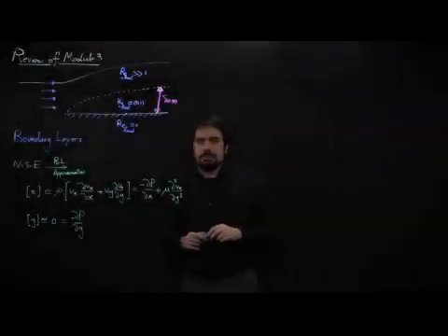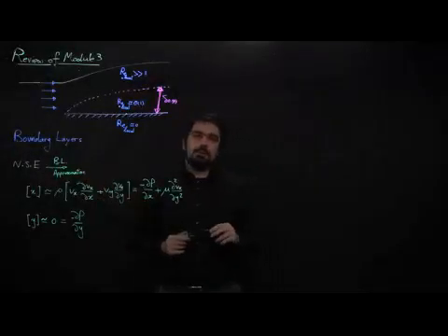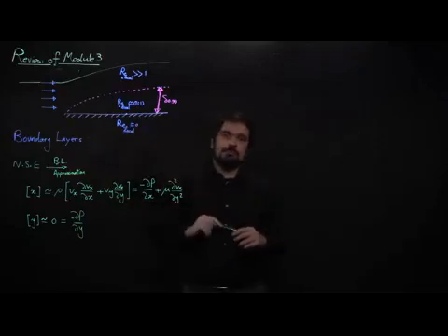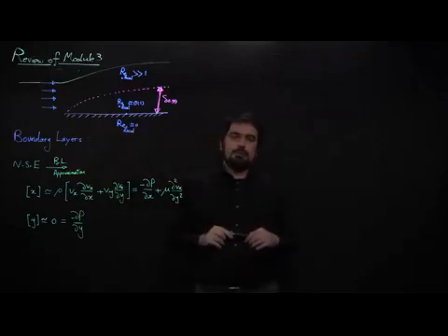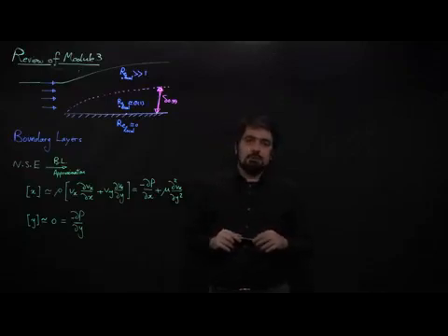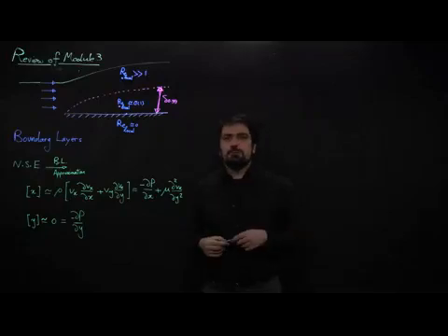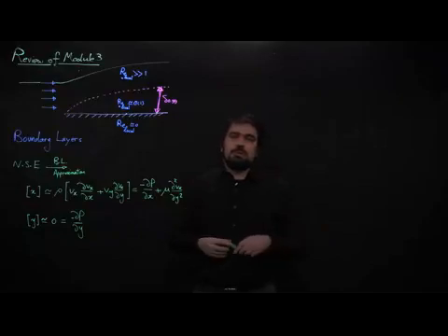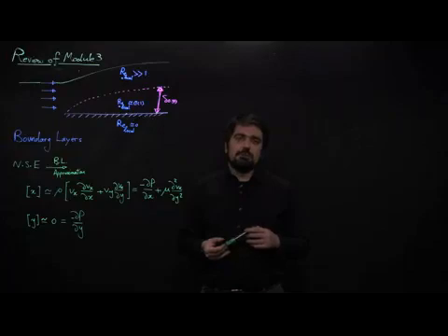Hi again. As we discussed in the last video, the idea of vorticity and the generation of vorticity at a rigid wall or boundary had to do with the no-slip condition in a real flow. When we discussed potential flows, the drawback was that we ignored the viscous terms, which are usually the second order derivatives. Because of that, our equation turned into a first order equation, and then we couldn't have all the boundary conditions that we had for the full Navier-Stokes equation.